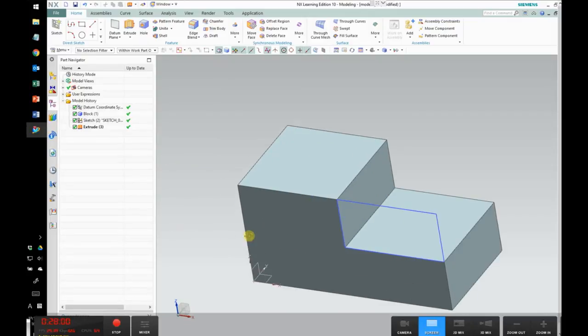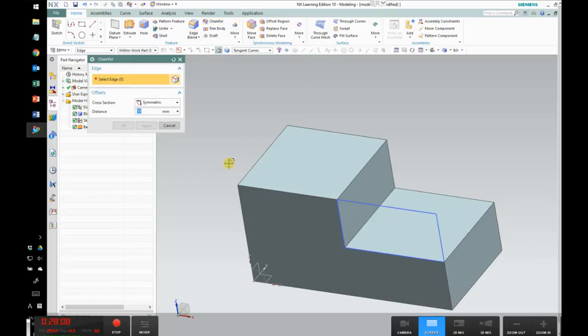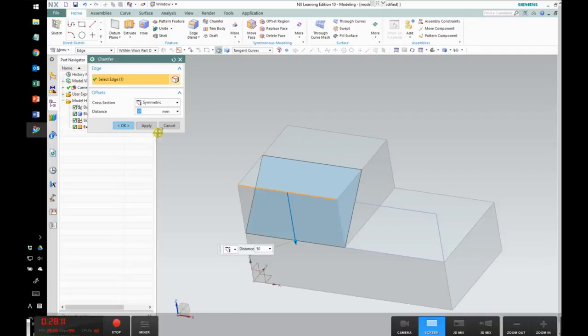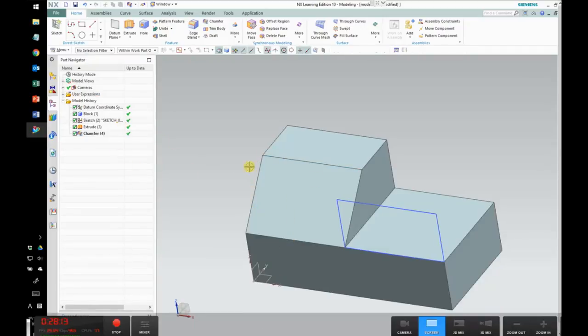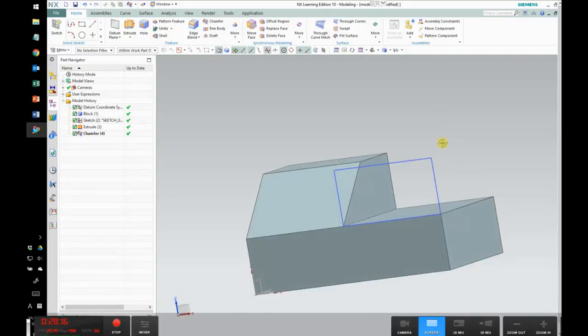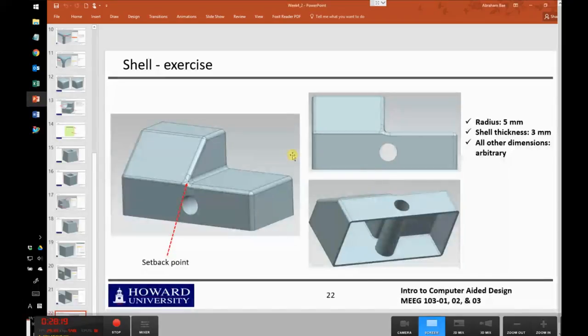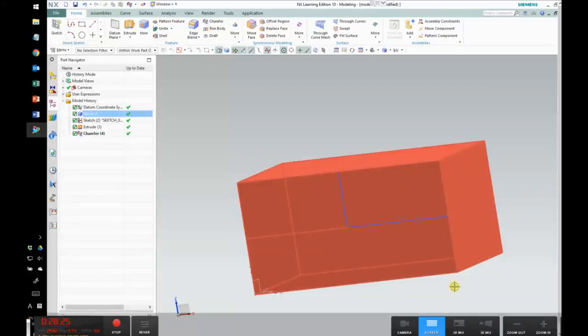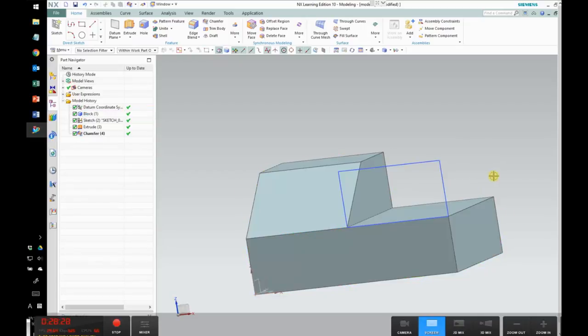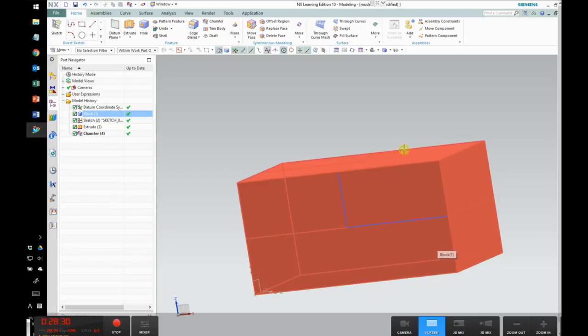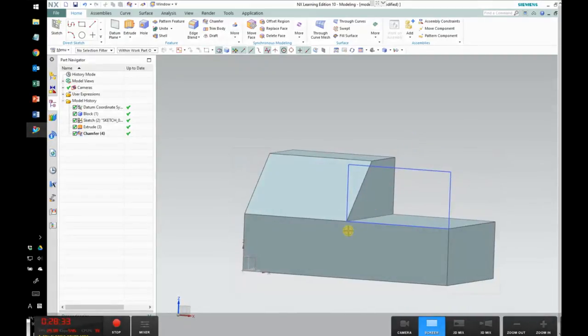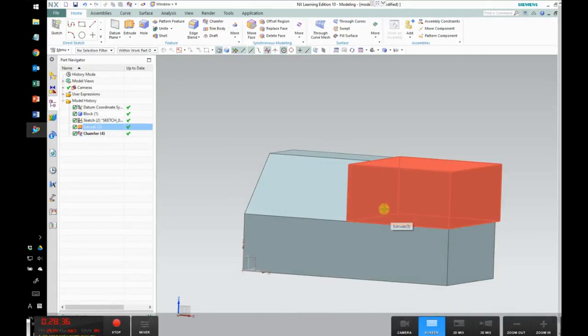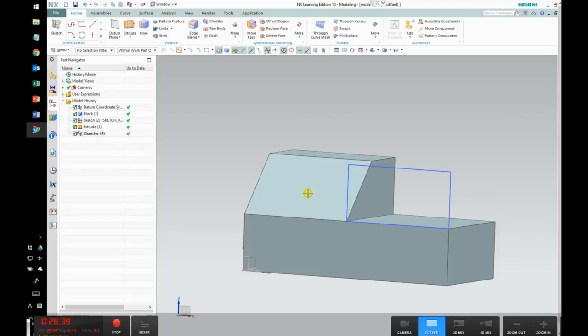And then let's apply chamfer here. Chamfer is right next to edge blend, and edge, this edge 50 millimeters. Okay, that's it. And then let's draw a circle here. Actually, the dimension doesn't matter when you do this exercise, as long as you have similar shape, and if you can do all that, you can apply all the functions I used, it's good enough.